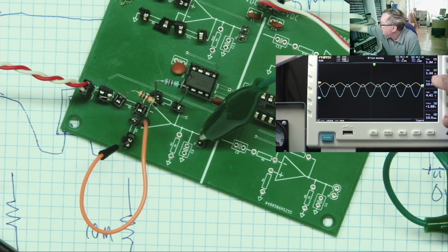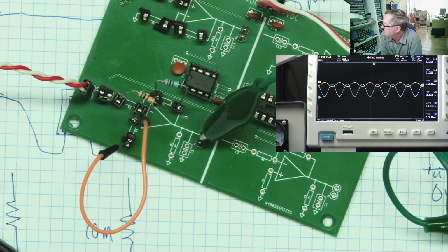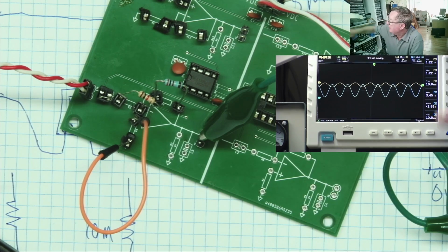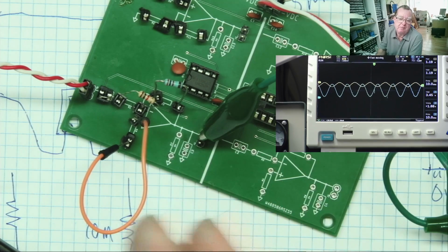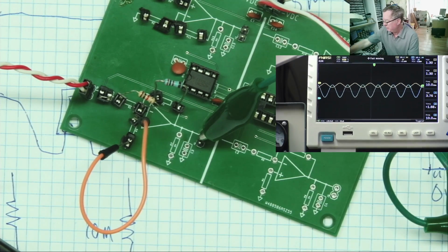And we can see that. So we have an input at the moment of about 1.2 and the output is about 3.6. So it's giving us what we expect, a gain of about 3 times. And we can clearly see that the output is inverted compared to the input. It's an inverting amplifier. And the question was, what will we see on the output of the op-amp if I turn the power off? So first of all, let's try it.